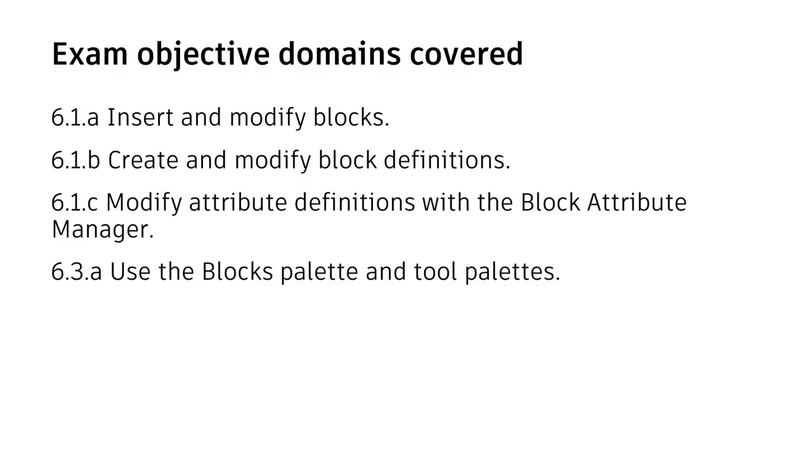Use the Design Center to access other drawings where blocks are stored. And also utilize the blocks palette for the same reason as well. The blocks palette makes that very easy as well. You might want to consider creating a central drawing where you store all your blocks in a single file to make it easy for you to locate and use your blocks library from a tool palette or potentially from the library tab on the blocks palette.